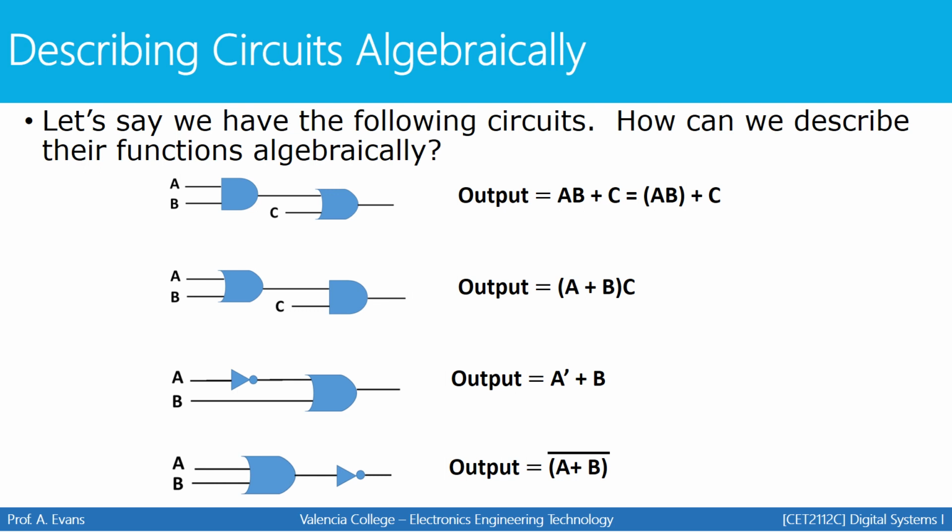Do not put two small bars, one over A and one over B. That's not what happened. What happened is the group went into the inverter, so it gets inverted as a group. One long bar over the entire group. This is how we start to write output expressions.